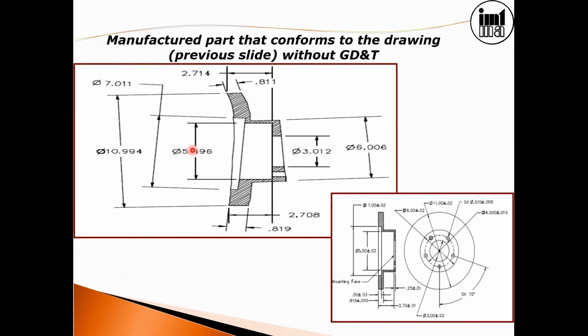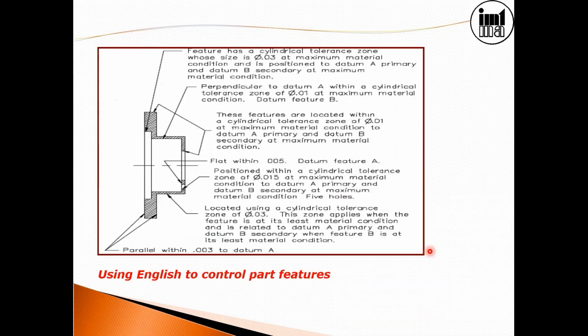How to solve this problem? As a design engineer, now we have to provide some more information on this drawing sheet, saying this surface should be flat, this surface should be flat, it should be concentric, it should be perpendicular, many faces should be parallel. All this information should be provided. Then the vendor will understand better. Let us write all these things like this.